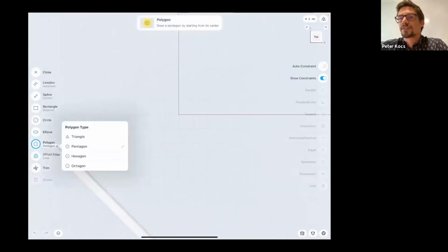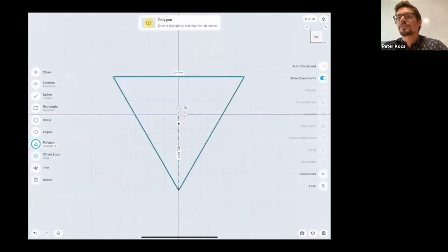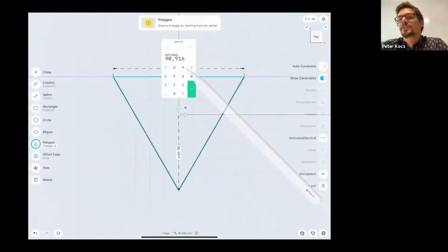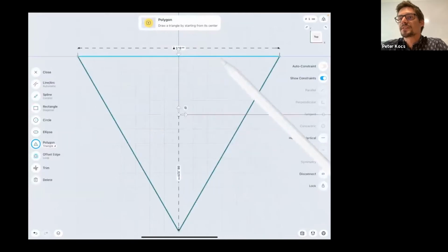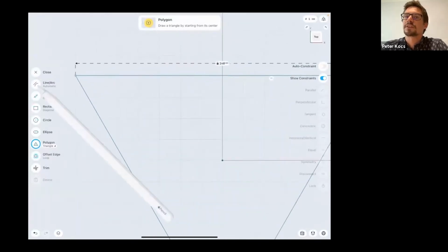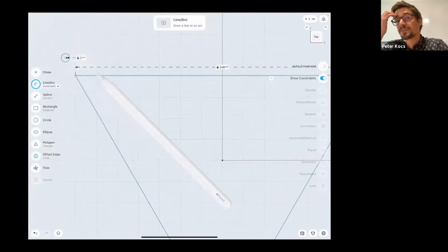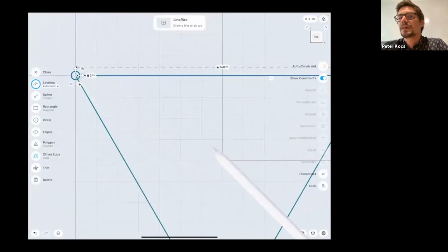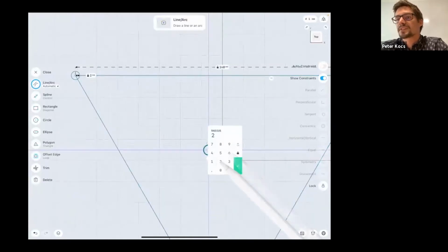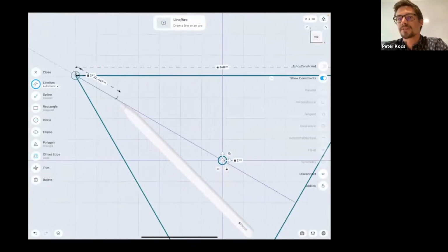The basic shape of this gripper is a simple triangle. So I'm going to start with a triangular polygon centered on the coordinate system of our workspace. And after constraining and dimensioning this triangle, I can move on to the cross-section of the vertical channels, which will be a simple circular shape with a 2 mm radius. Then let me do a second one, and then I will need one more reference that connects the 2 circles together.